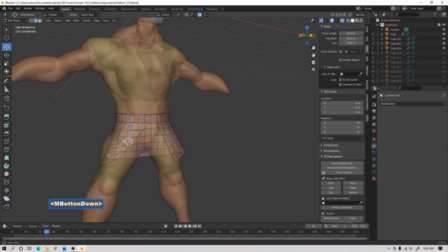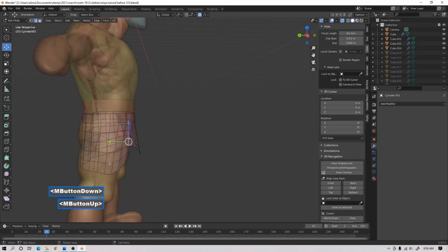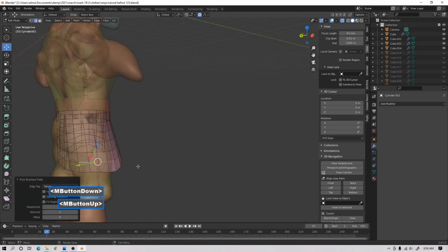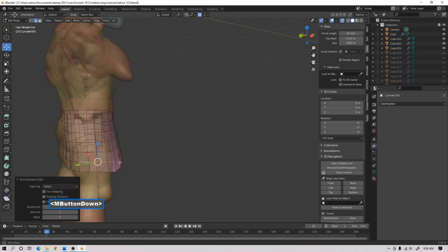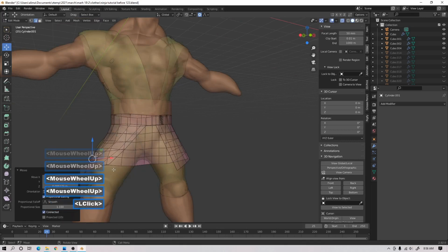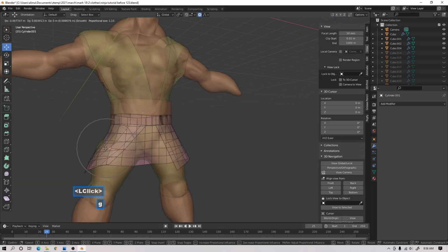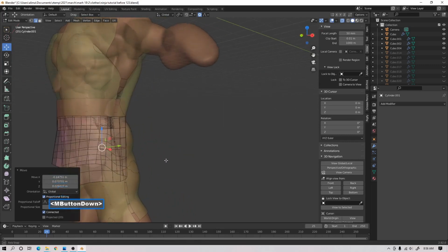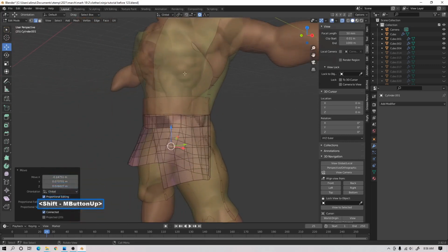So now we'll select here, hold Control. We use the shortest path technique. When I held Control, I selected here. I selected here, held Control, selected there. Blender connected the points in between. So basically, what's going on here is, think of this being connected to that.